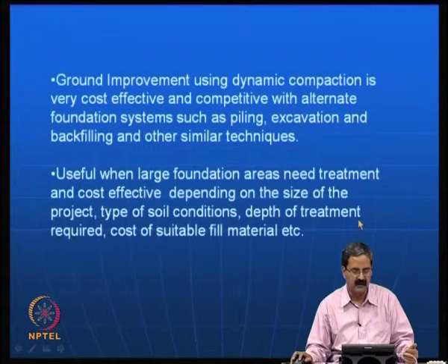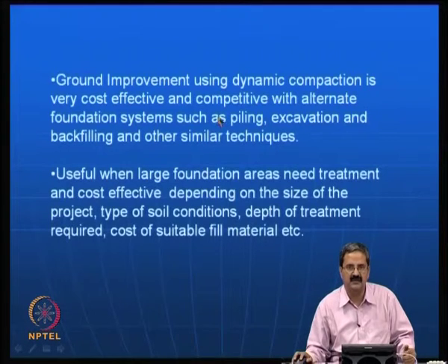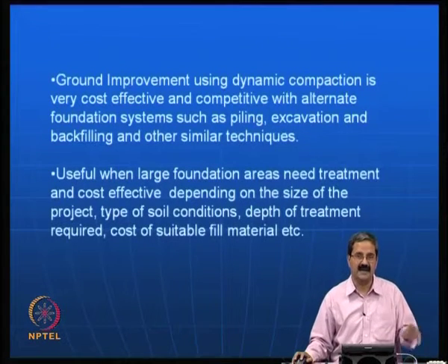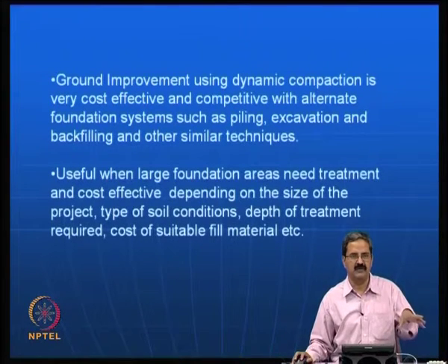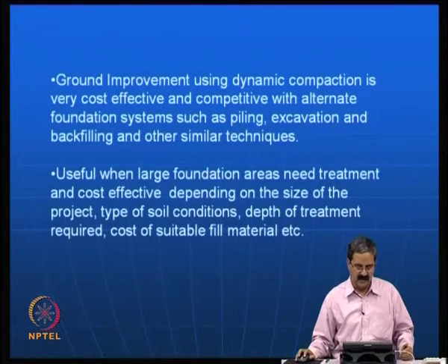That was what I meant, and particularly these people have explored a lot of other options in the site, like other similar treatments, like removing the whole soil and backfilling, and some of them like trying to do the piling. So, for example, if you want to increase the bearing capacity of the foundation area, why don't you go for piles, why do you go for just simple compaction, which we do not know much. So, it depends on the consultant that the project has. If somebody is a geotechnical consultant, he will be able to give geotechnical alternatives, but if there is a structural consultant, maybe he may recommend piles because he has a lot of confidence.